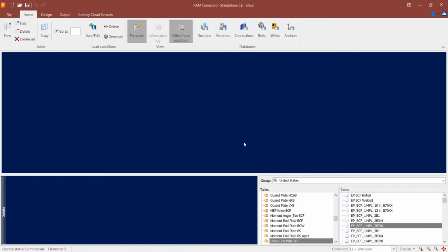Now, if I come back at a later time and add some additional load cases, you will want to come back and regenerate your load combinations to make sure that they are included, particularly if you add load types that were not already included in the program, such as like wind or seismic. You're just going to want to regenerate those load combinations.